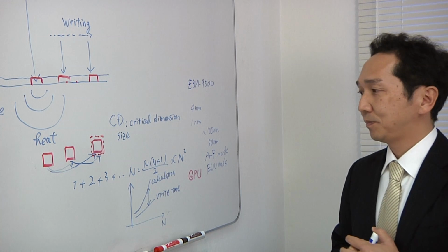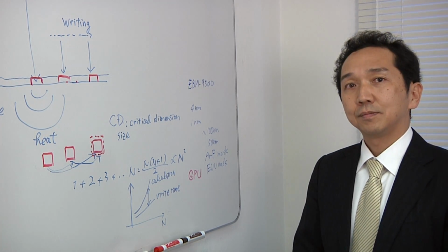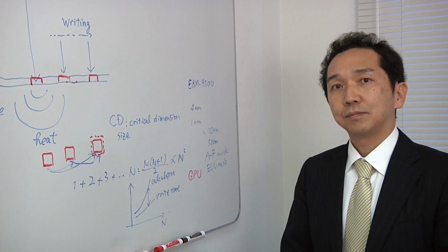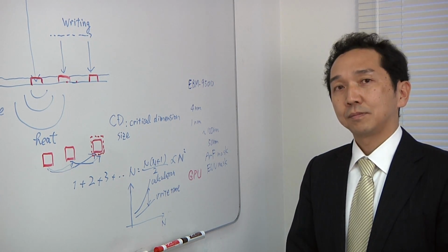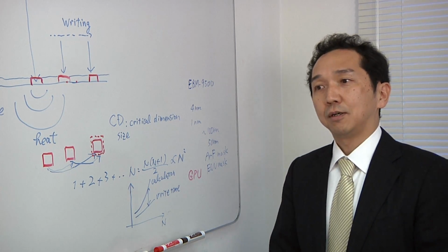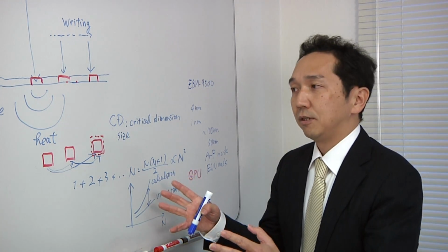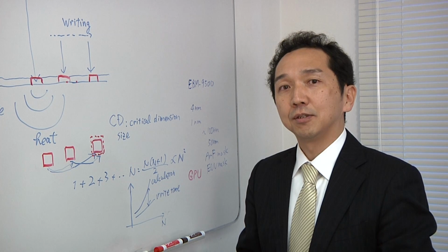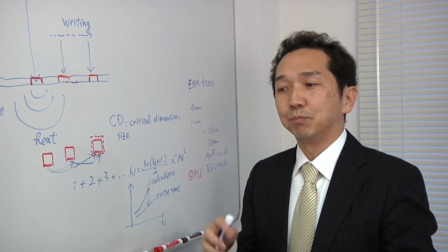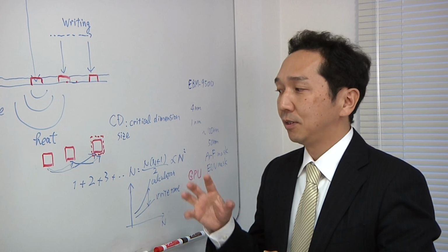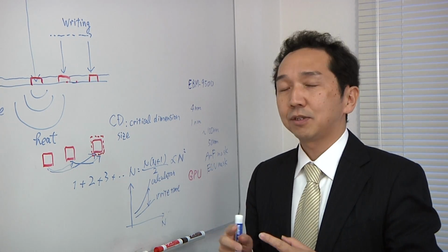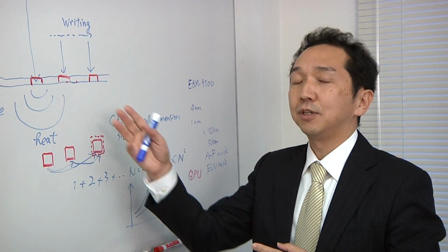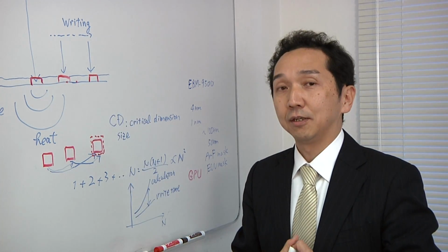Okay. So when you get all this done, are we still staying current as we move down from one node to the next and one mask problem to the next? Are we still able to maintain a consistent amount of time that it's going to take, or are we falling backward? That's a good question. The entire life of VSB, single beam technologies, is already ending, and we are making next platform using multi-beam systems. And in multi-beam system, we handle pixel data instead of shot data, which is essentially rectangle data.